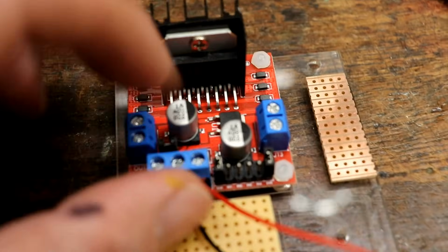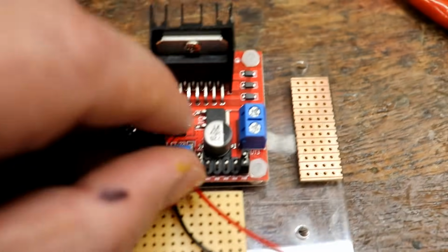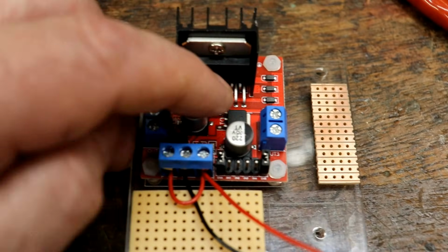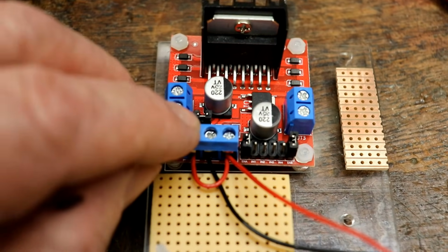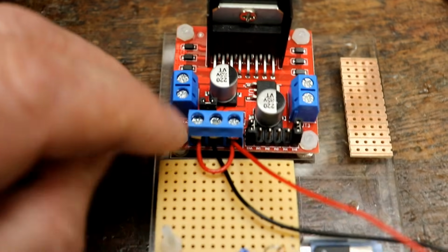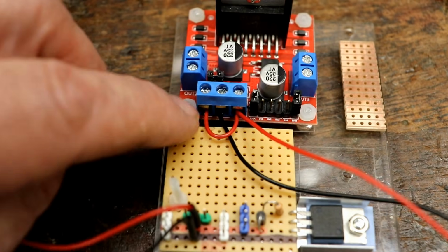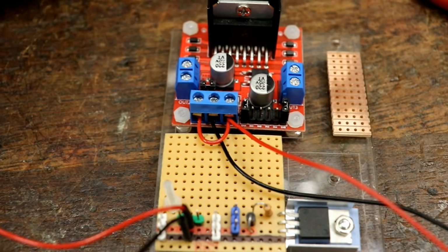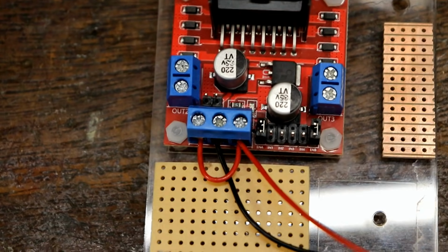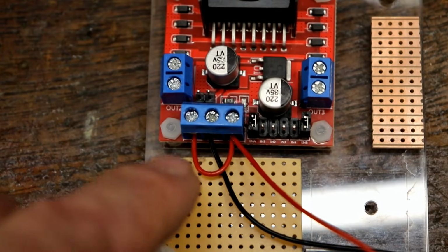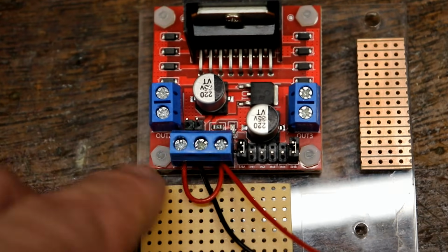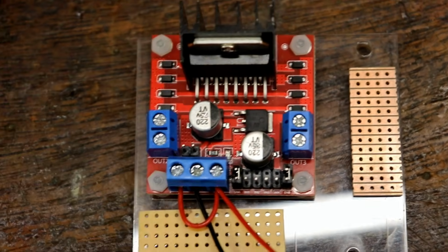what you need to do is get rid of the little voltage regulator there, the 5 volt regulator. We don't want to use that, we don't need it. So we're going to pull that little link out, and we're going to connect 5 volts to both of those inputs. There we are, the little link has been removed. So now we're providing the 5 volts for the logic and the 5 volts to switch for the motors.